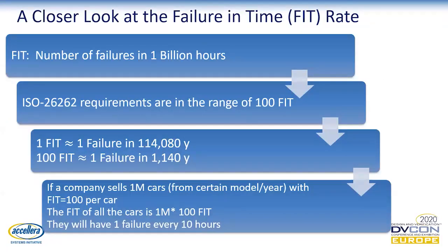A closer look at the fit rate and how important it is. The fit is defined, as we defined in the last slide, as the number of failures in 1 billion hours of operation. ISO 26262 requires that a range of 100 fit rate is assigned to each one. So that means a 100 fit rate means one failure in 1,000 years. Oh, this is like no failure at all, right? 1,000 years, no failures. But let's have a different look at the fit rate.